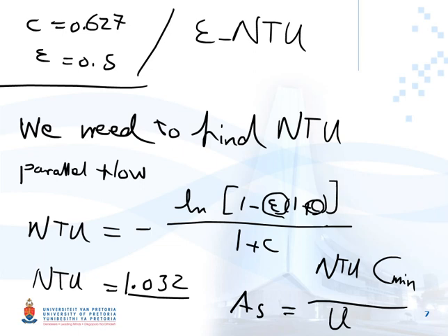When you have calculated the h, you repeat the same process for the other h, because as I said, we need two heat transfer coefficients to calculate the overall heat transfer coefficient. So you put those two values into the correlation that you first wrote for the overall heat transfer coefficient, and you calculate it.